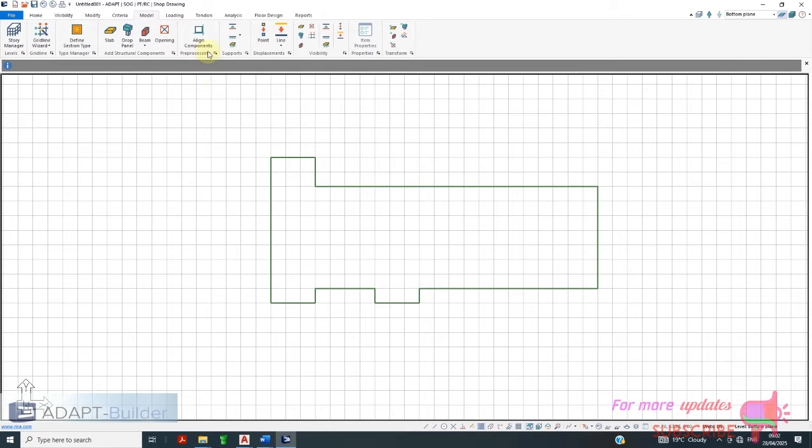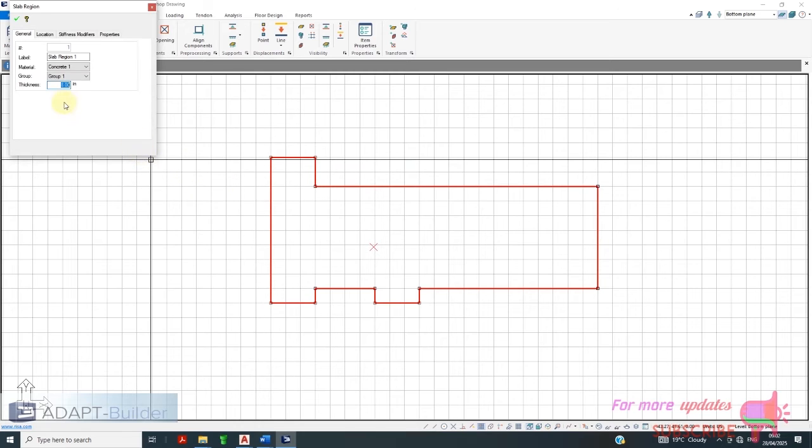So you can go to activate item property. So this is my slab. Then my slab is 8 inches thick. I can change that one to 4 inches. Modifier, stiffness modifier, properties. Then you click on that. Is it green tick? So that one has been activated, and then you can close.